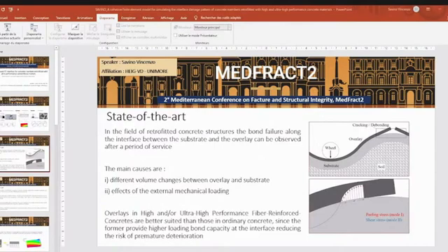Modeling the bond response of retrofitted concrete members represents a relevant challenge due to the high number of mechanical parameters affecting the phenomenon. Bond response also depends on the field conditions, like the moisture level of the substrate surface prior to the application of the overlay and the fresh properties of the latter. Their effects on the development of bond capacity are still controversial. The few available numerical models able to reproduce this phenomenon are complex for practitioners, who tend to simplify the numerical simulations by using tight interface conditions. A drawback of these models is that the bonding failure cannot be directly observed, so the bond performance would be drastically overestimated.